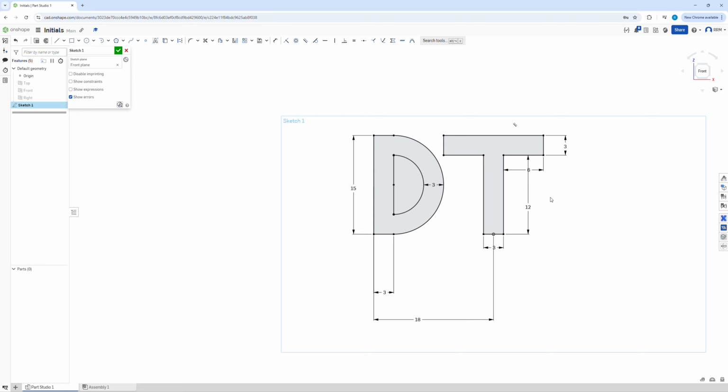And that is the start. We could then make the E. I'm not going to do that because we've kind of used pretty much all of these. If we wanted to, just to give you a demonstration, this won't work, but it will hopefully make sense. We can get this line here tangent to here, and then that has basically lined this line up exactly. If I was to draw a construction line down between the two, you can see that it lines up perfectly. Okay, so it's made this tangent here, so that lines up there. Everything else I think we've kind of covered.